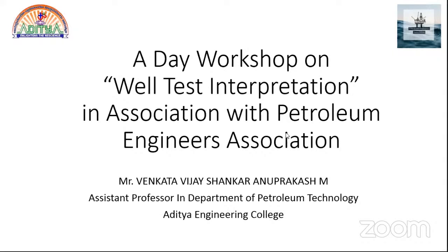For the isochronal test, when you shut in the well, why does the pressure return to the original pressure? See, actually theoretically it works, but in a practical sense it is not possible. That is why there is an alternative to the isochronal, the modified isochronal test. We can't reach it. Technically, it is very difficult to reach the original condition. That too, it is only possible with gas. If it is oil, there is no way.